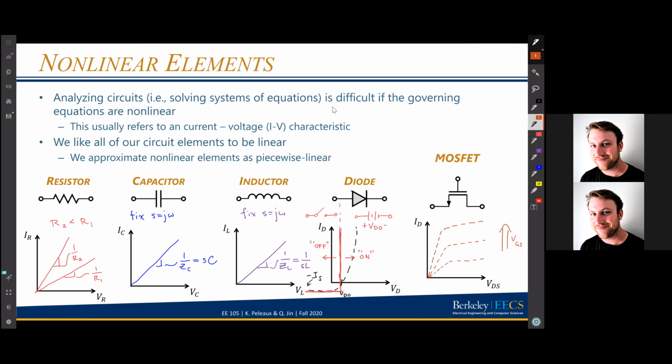And you'll learn more about this later, get more comfortable with these MOSFET IV characteristics later. But given a fixed VGS, so I'm going to fix VGS, then let's say I fix it in the middle, then I can actually take my nonlinear, clearly curved function and create a piecewise linear model again, right? Where I take the slope of the linear region and keep that constant up until the knee. And then I take the slope in the saturation region and keep that constant past the knee. And so again, we have two regions now that we've created, but in each region, this device has a linear IV characteristic.